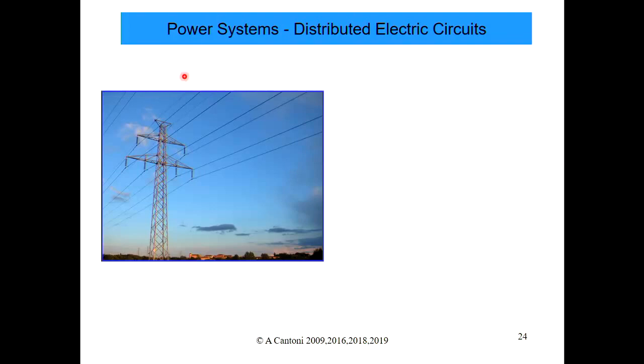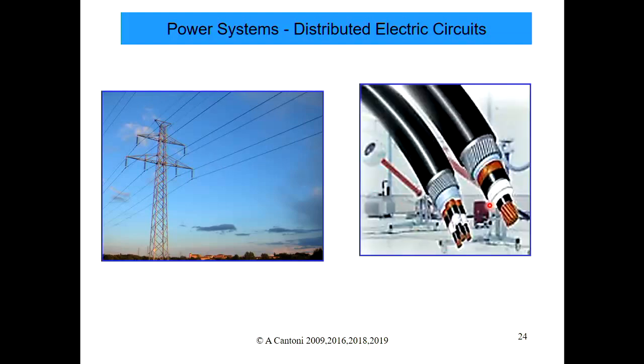So as you mentioned earlier, power systems, okay? What you thought of as a transmission line, which is true. This is a transmission line. Now, it's working at low frequencies, but it's a very large size, okay? So it's not just the frequency that's important, it's the relationship between the frequency and the size of the circuit, okay? That's the critical thing. So power systems, when they're going over a large distance of thousands of kilometres, then you probably need to model transmission line aspects of that, okay? And at high frequency, you have all this sort of stuff.